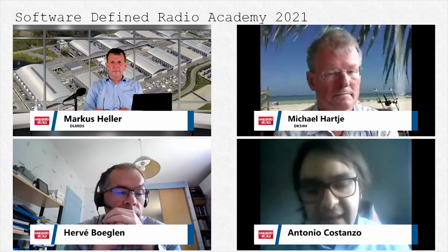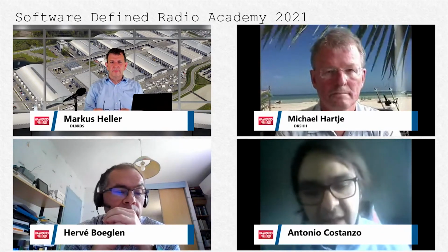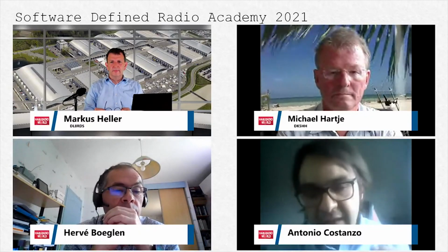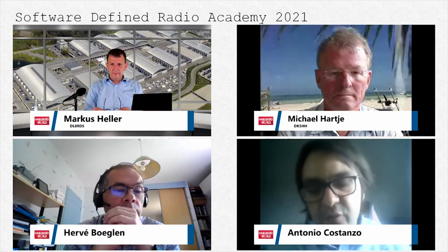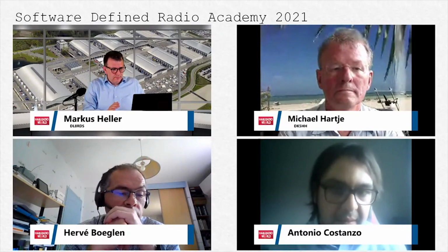You just need the other daughter board, but in the meantime, you need some amplifiers, or something in order to allow the signal to go in the correct dynamic, I mean, between -1 and 1 volt. Because if you use a simple receiver, you can easily saturate the input of the receiving USRP. So you just have to be really careful with the dynamics. But otherwise, you can just design the system as described in the literature. Just a few changes.